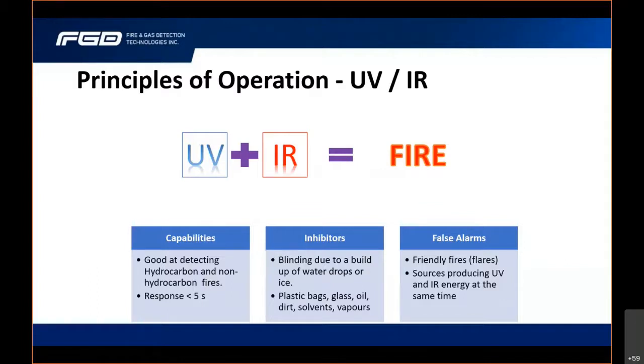Here, the great benefit was that you actually had virtually no false alarms for these two detection technologies that would coexist, which means that having a false alarm itself was extremely difficult. But the challenge with those technologies is that anything that would affect the UV channel and stop it working, or anything that would stop the infrared channel and stop that working, would mean that the detector may not perform when it was needed to. Today, UVIR detectors are one of the two main technologies that are actually being utilized.